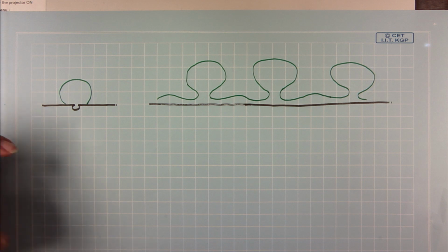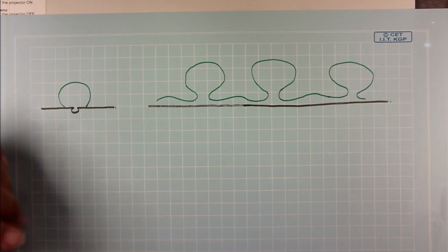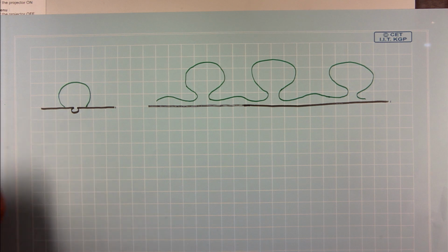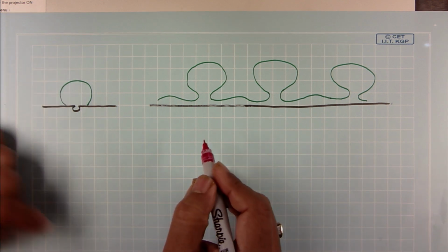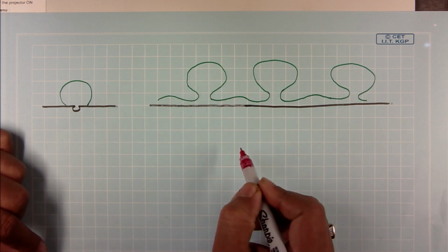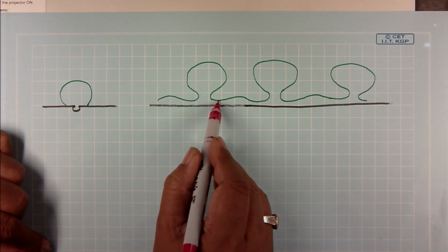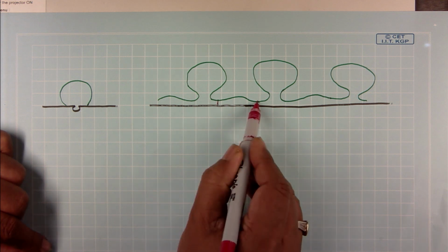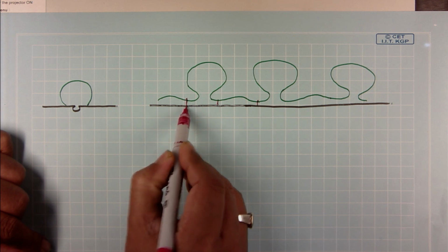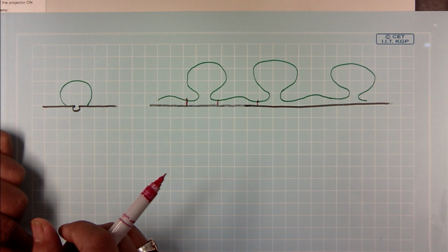If I think about the heat transfer in film boiling, how is the heat transfer occurring? It is by conduction and radiation, right. Radiation is almost uniform, but your conduction heat transfer will not be uniform. So, wherever I have a minimum thickness in the vapor film, that is where I am going to have the highest heat transfer, is not it?